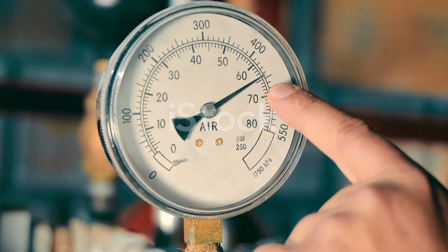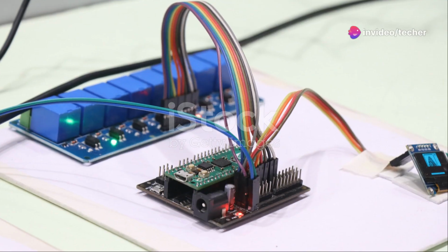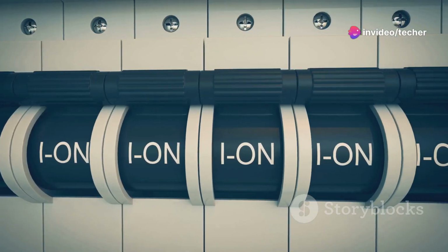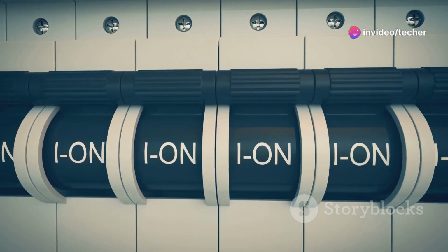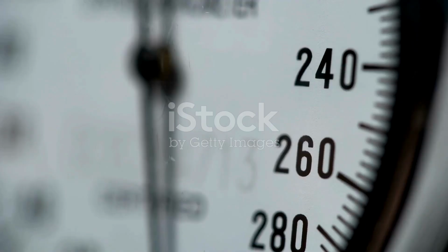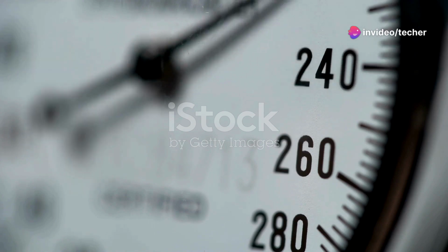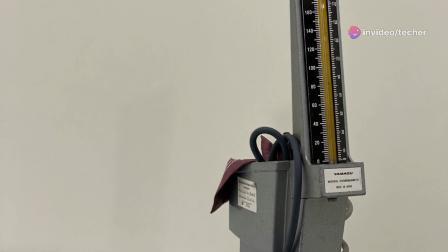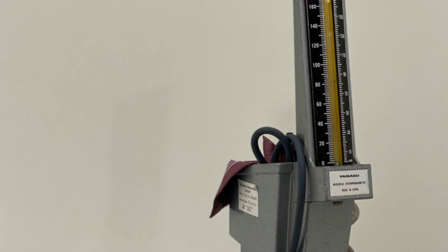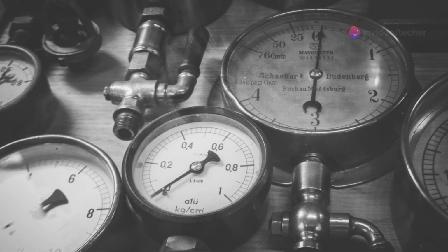Lastly, let's explore digital pressure sensors, which excel in applications requiring precise on-off control based on pressure thresholds. Their ability to deliver clear-cut signals, indicating whether a specific pressure level has been reached, makes them ideal for triggering events or activating alarms. Digital pressure sensors typically incorporate a pressure sensing element, similar to those found in analog sensors, but with an added layer of signal processing. This processing circuitry converts the analog pressure signal into a digital output, often a high or low voltage level, representing the on or off state.